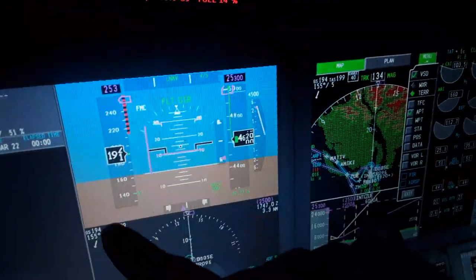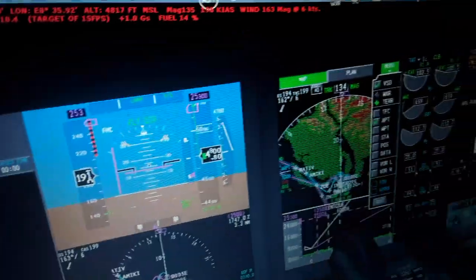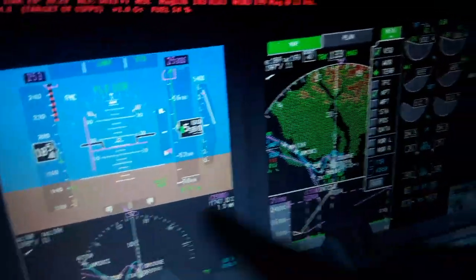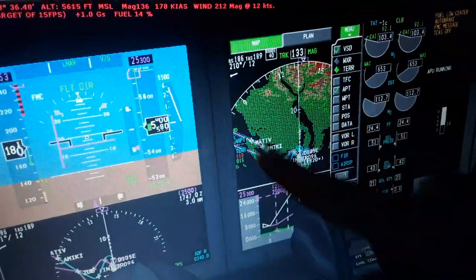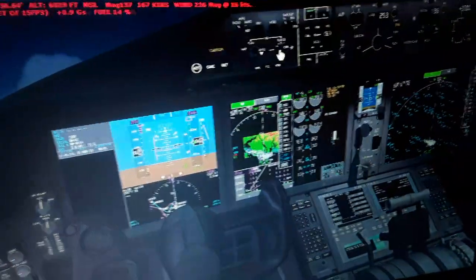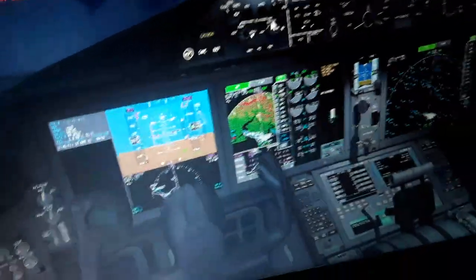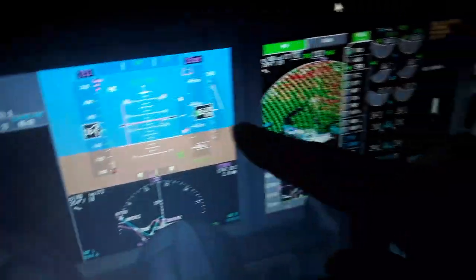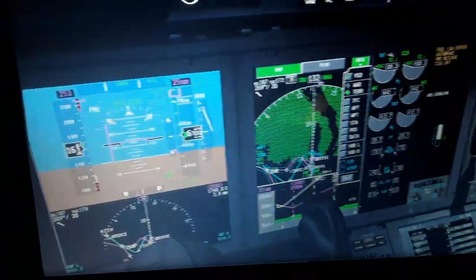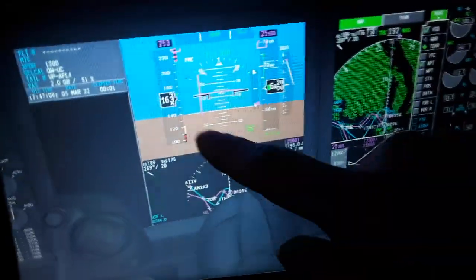You can see the airspeed, the wind direction, the stall speed. We climb with 4,000 feet per minute right now, 5,000 feet per minute. You can see the trend line. Also the runway LSZH localizer. Here are the flight plan, the terrain, red, green, yellow. Terrain indication, the pitch attitude also. If we climb the pitch attitude, we're gonna have the stall speed coming in, so we decrease the pitch attitude. Also you can see the terrain over here, the engines, terrain below the aircraft and around, stall speed here, marking with the red and yellow.